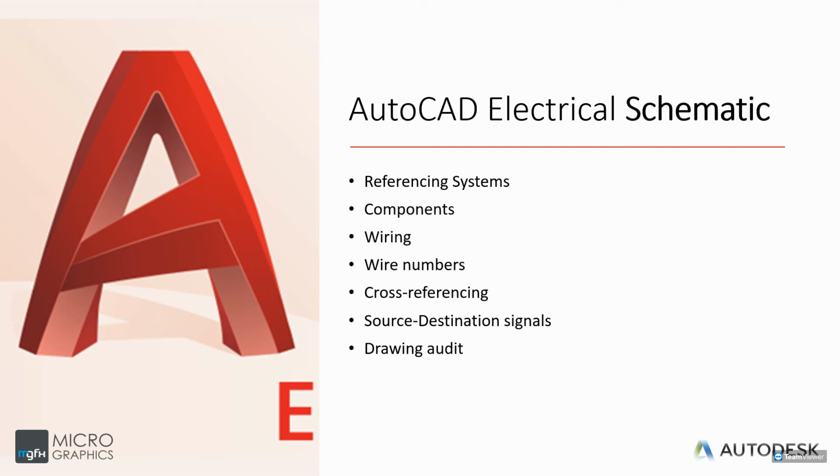Okay, if you look at your properties, either in the drawing properties or in the project properties, remember we said the project will apply them to all the drawings inside here. We've got cross-reference styles. We have 3 types. We've got text format, graphical format, and table format. So you can see what your table of cross-referencing will look like when you do place it. Okay, so you can customize each of these things here. If I look at that, this is the graphical format. It gives you a little preview of how it looks in here.